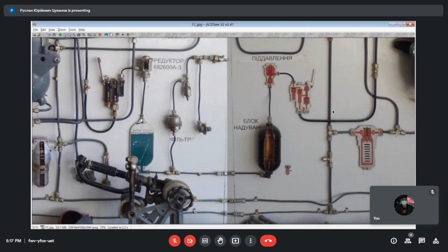From the other side, the bottle has an outlet connected to the pressure regulator. This is a picture of the actual structure of the pressure regulator. The pressure regulator should reduce air pressure from this bottle to one suitable for the hydraulic tank. Of course the bottle contains higher overpressure than the hydraulic tank, to provide pressurization during some time.